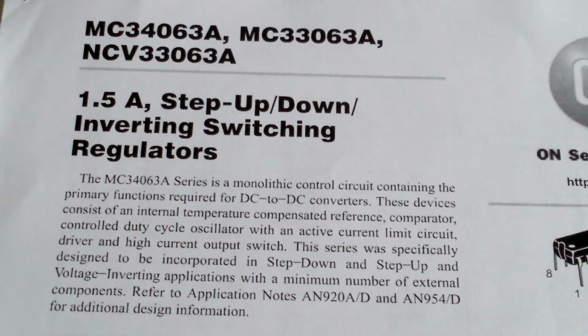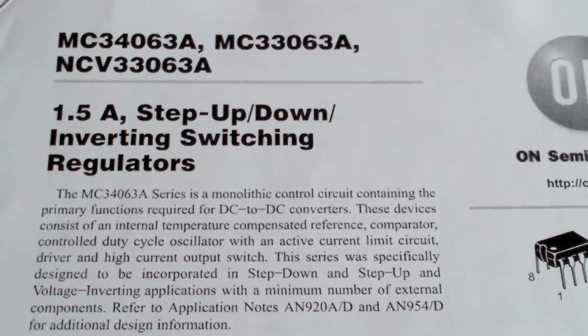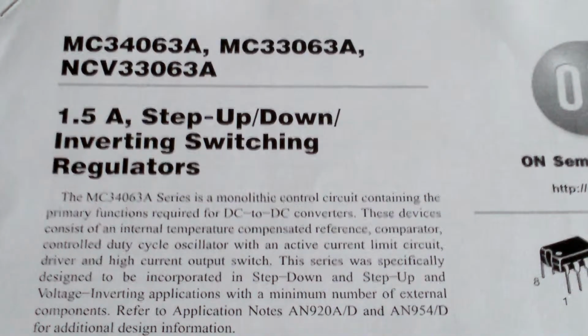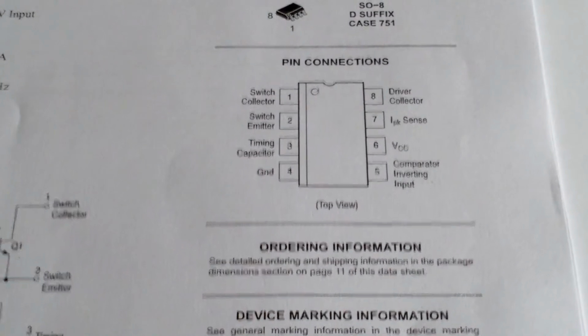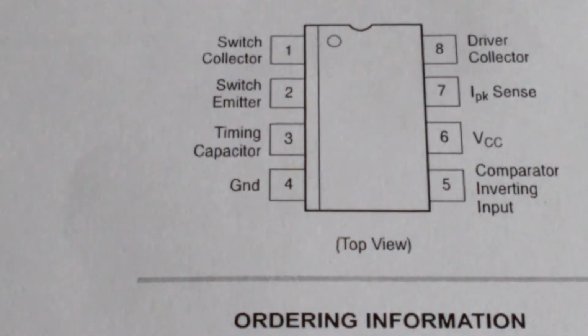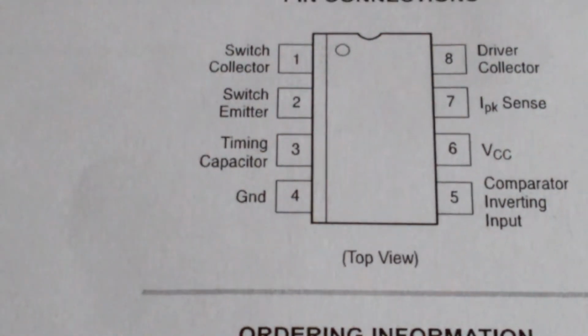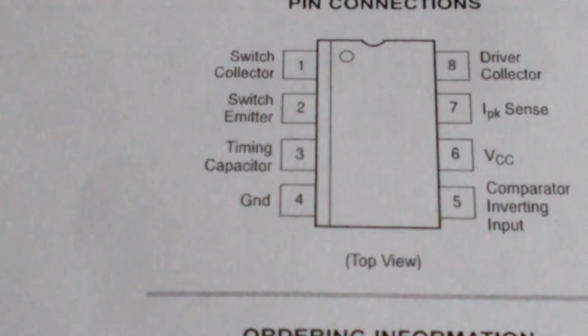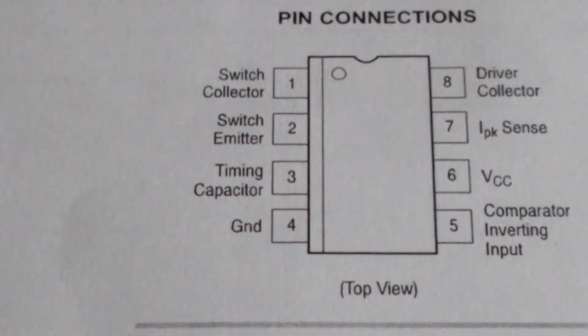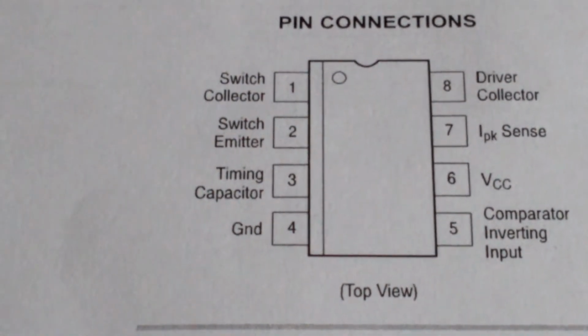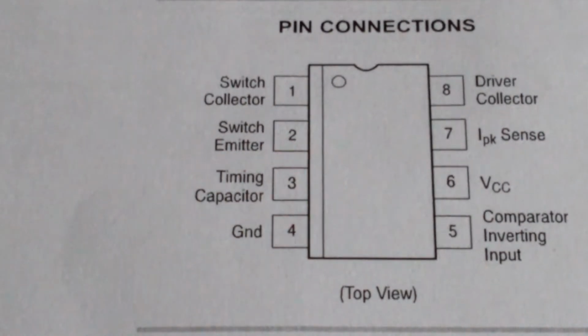So we are going to use this very popular chip, the MC34063. This is an 8-pin chip. Pin 1 is your switch collector.